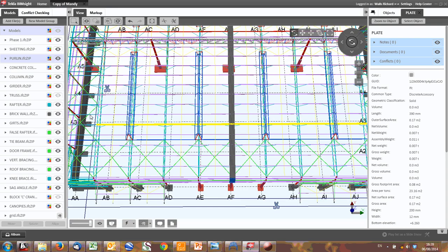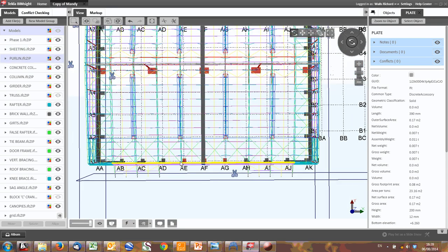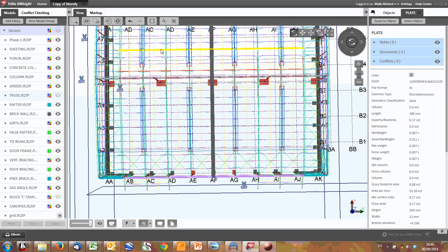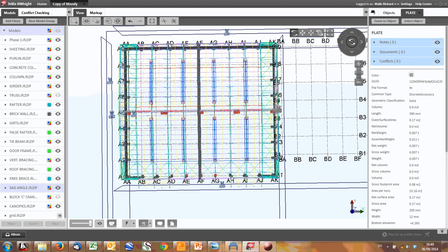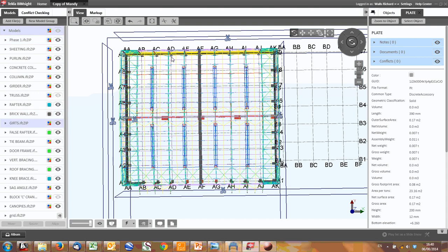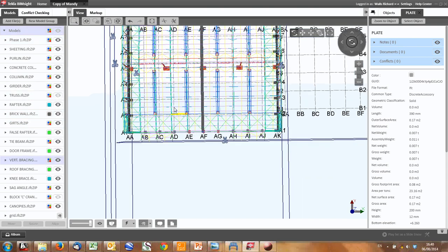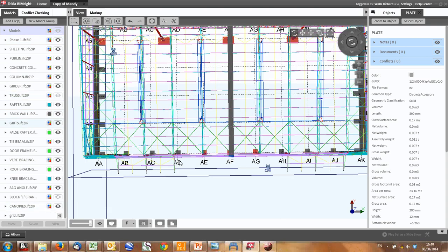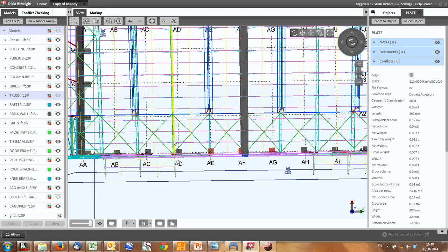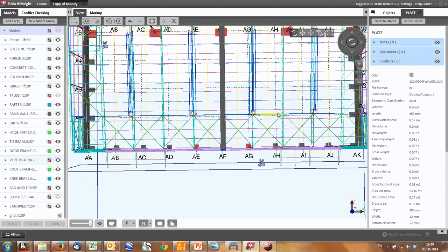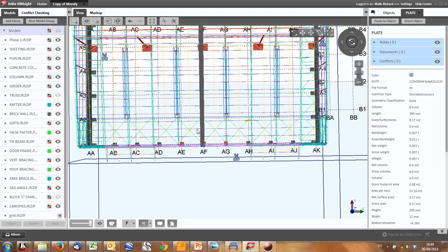It's basically like a giant truss all the way along the edge. So if the wind comes from the top, pushes down on this truss along grid line AD, pushes, pushes, pushes, it comes all the way down the truss to here, and at the same time, the suction pressure is pulling this down. But this very stiff truss, this very deep truss almost, prevents it from moving. And that provides the lateral stability.